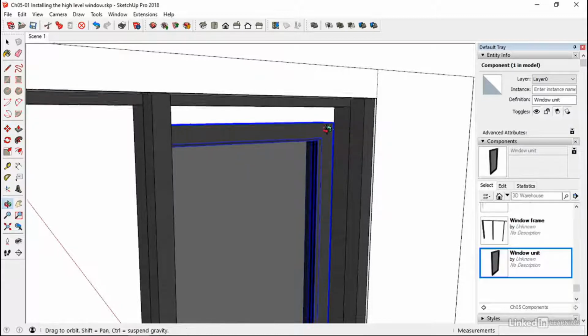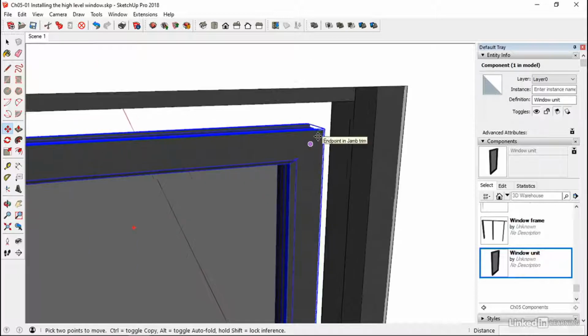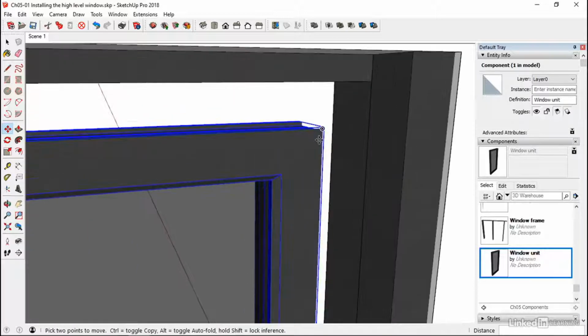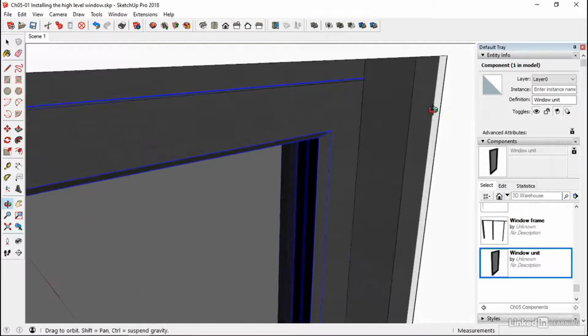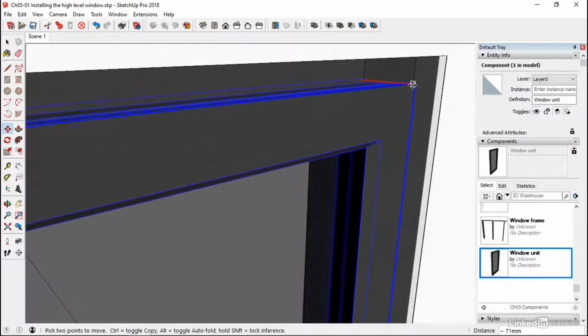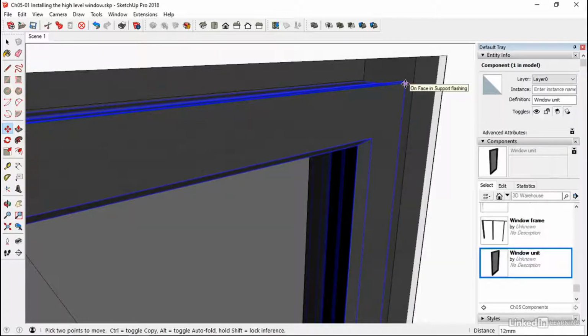So quite nice. And what we need to kind of do is grab this top corner and pop it into that sort of position. And then it's about 15, 16 mil, or it's about 5/8 of an inch from this front edge. Again, it's not massively important. So this whole distance is 71. So if I just bring it forward to that point there, it kind of sits inside this bit, and then back about 16 mil, that's 5/8 if you're using Imperial.